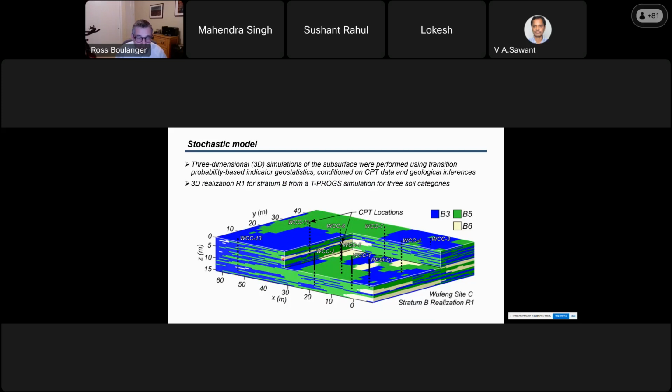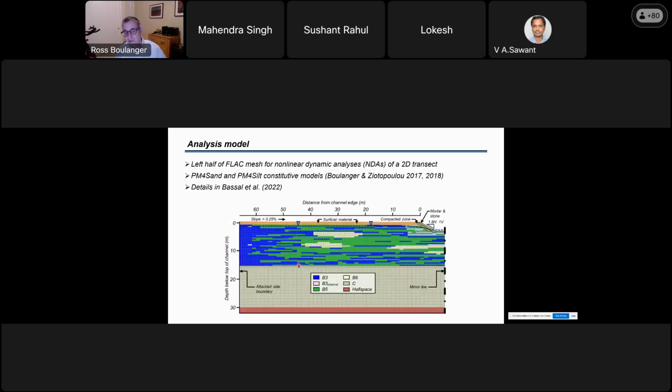And here, you see this yellow layer is an easy one to point out. That layer is continuous in the direction of the channel, but it's not continuous in this direction. That's because you have to constrain it by understanding the direction of water flow. Features will be more correlated up and downstream than they are cross-channel. And you need that kind of geologic model insight to run these types of stochastic models. We then cut 2D sections.